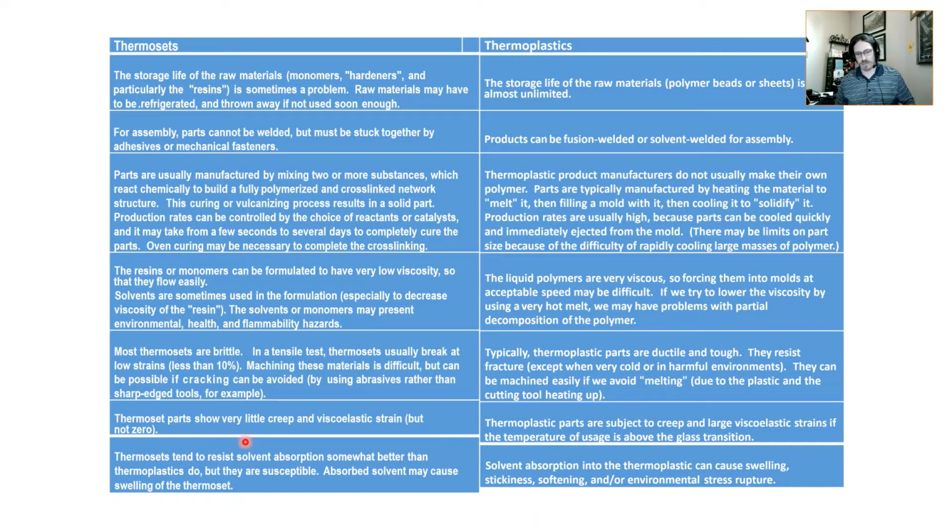But composites, like the so-called graphite epoxy composites, the matrix a lot of times is a thermoset epoxy, and you're overcoming some of the problems by putting in the carbon fibers. That's why you make a composite, to either achieve a new physical property or to overcome some problem with the matrix. Some of you may be taking or have taken composites, and you're well aware of that. Anyway, I'll let you pause it if you're interested in this material.